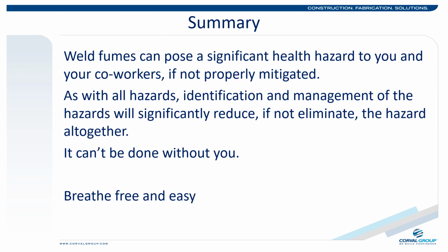In summary, to ensure your safety and health, as well as the safety and health of your coworkers, always identify the flow of weld fumes and make sure that they are not being breathed. Identify the hazards on your task hazard analysis, THA, and work with your supervisor to ensure that the work is being performed in the safest manner possible.